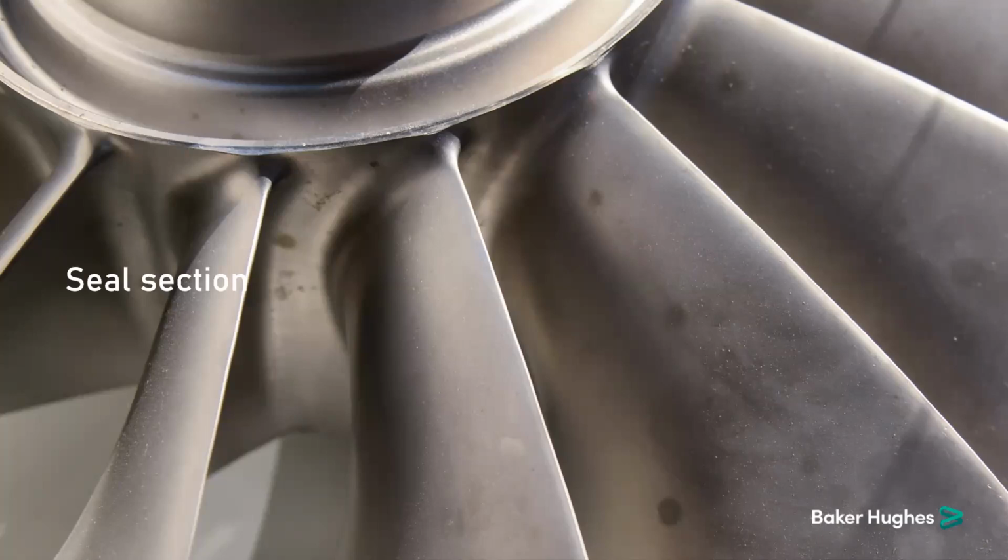Can the pump be installed on the power cable? There is an application from Baker Hughes called the cable deployed system, where the ESP power cable is utilized as the power cable and the carrier cable at the same time. Approximately three systems are installed in Saudi Arabia with Aramco, and this is an existing application for installing the pump with the power cable.